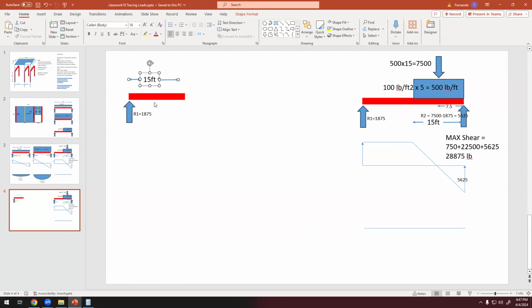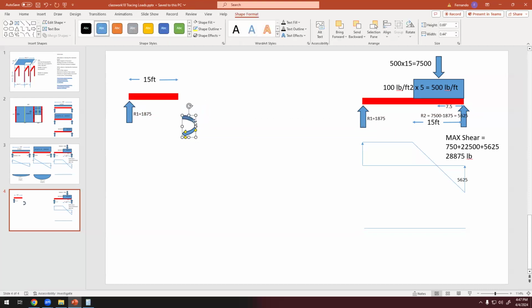So the beam length is 30. I'm cutting that beam here before we notice the uniformly distributed load. So what do we have here? We have just the reaction, because we don't have any load in this half of the beam. If the reaction is moving that beam in this direction, there should be an internal moment here.